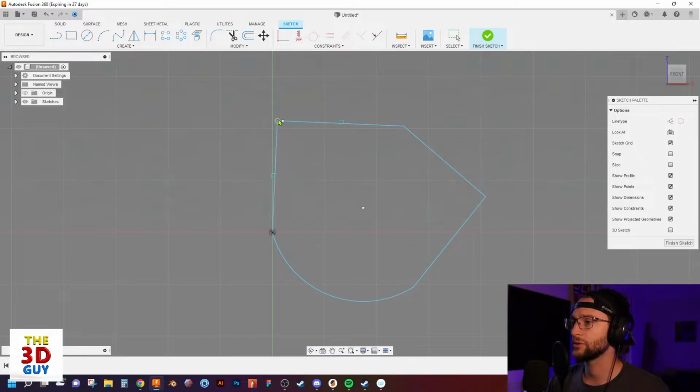Now you should even be able to go past the line. Nope, it doesn't actually continue past the line in this situation. So you do have to be on the line if you're going to be dragging it. You can also go to the midpoint, which you see right there has that triangle. This is actually really nice, especially if you're looking at something like cams. It really opens up a lot of possibilities of quickly placing all of those constraints.